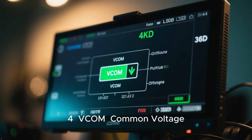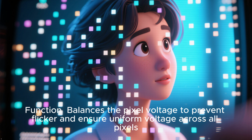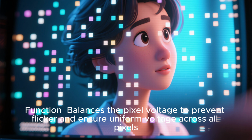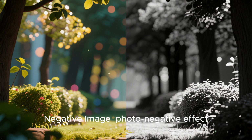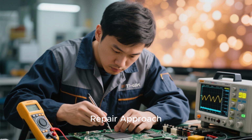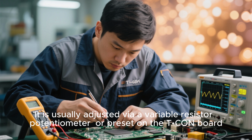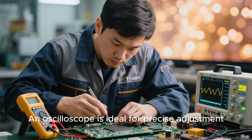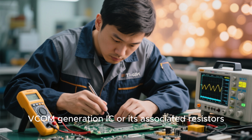4. VCOM, common voltage. Typical value around 5 volts, often adjustable. Function: balances the pixel voltage to prevent flicker and ensure uniform voltage across all pixels. Symptoms: if missing or incorrect, white screen, negative image, negative effect, ghost image. Repair approach: this is a critical voltage. It is usually adjusted via a variable resistor, potentiometer or preset on the TCON board. An oscilloscope is ideal for precise adjustment. Faults can also lie in the dedicated VCOM generation IC or its associated resistors.